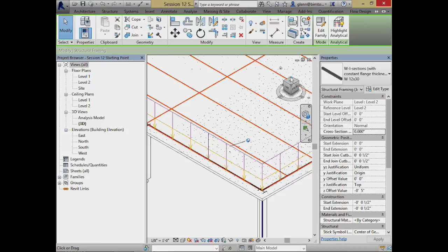If you're a structural engineer, push it further in terms of really understanding how different things that we do within Revit get used in the analysis tool. So, if that just basic framing is looking very basic, think about, if you have shear panels or shear cores or something like that, how you can analyze both the steel and the concrete as some sort of composite structure and play around with it on that side. Because the capability is there.